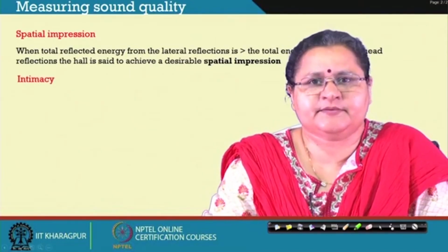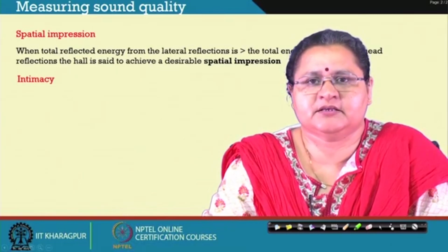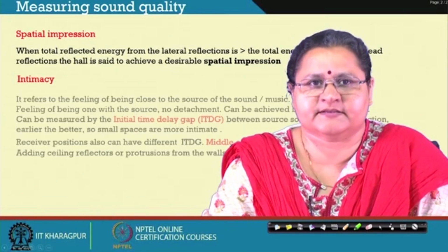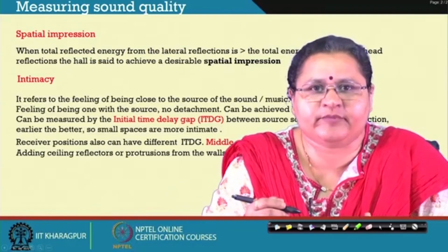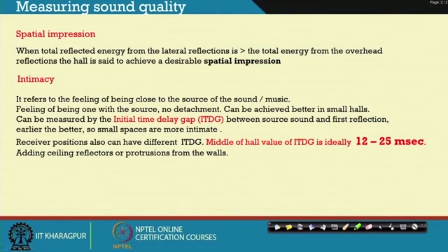Coming to intimacy, we know the word intimacy means closeness. So, it refers to the feeling of being close to the source of the sound, which here we are accounting as music. So, the feeling of being one with the source, that is not being detached, is the concept of intimacy. And how to measure it? That means the initial time delay gap, that is the gap between the first source sound and the first reflected sound. The smaller the gap is, the better is the intimacy.